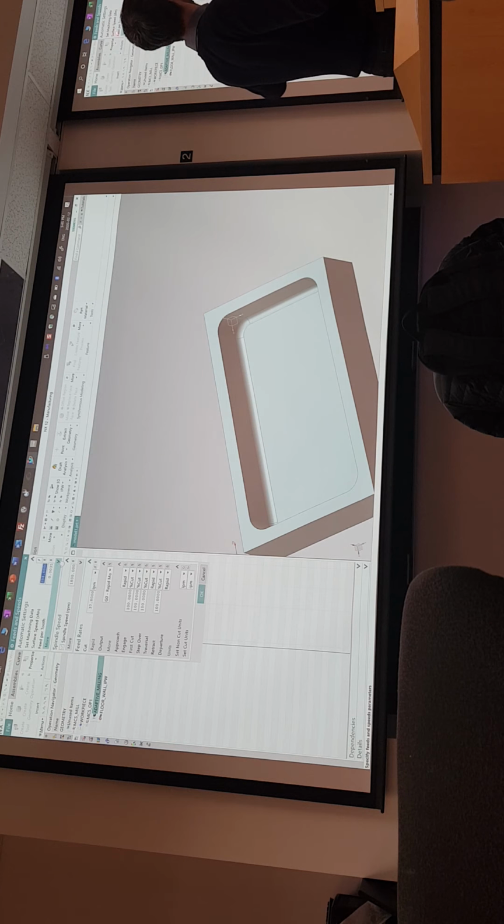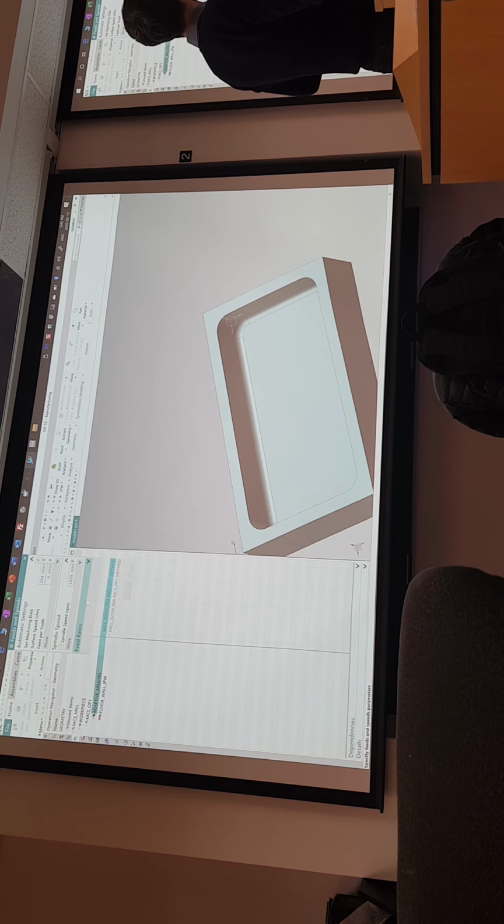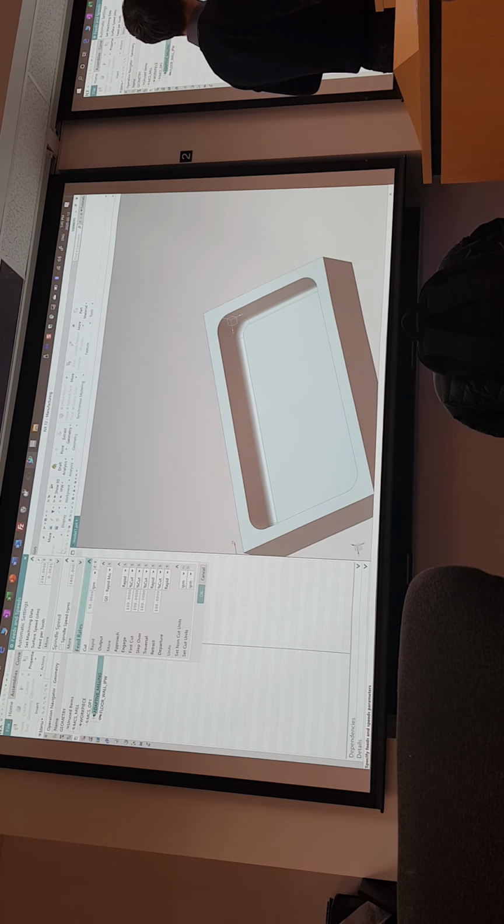You fill in the surface speed, the feed per tooth, as long as you define the correct number of flutes in your tool, your spindle speed and your cut speed, and then if you change any one of these, it should back calculate the chip load, for example.